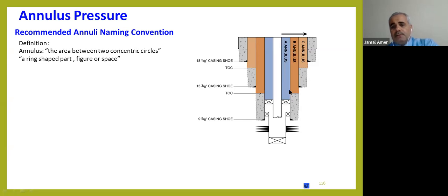So here, as I told, we have to identify the source of pressure immediately to take the correct actions, either from the Christmas tree or by doing corrosion logging or acoustic logging, to find the bonding between the casing and cement.